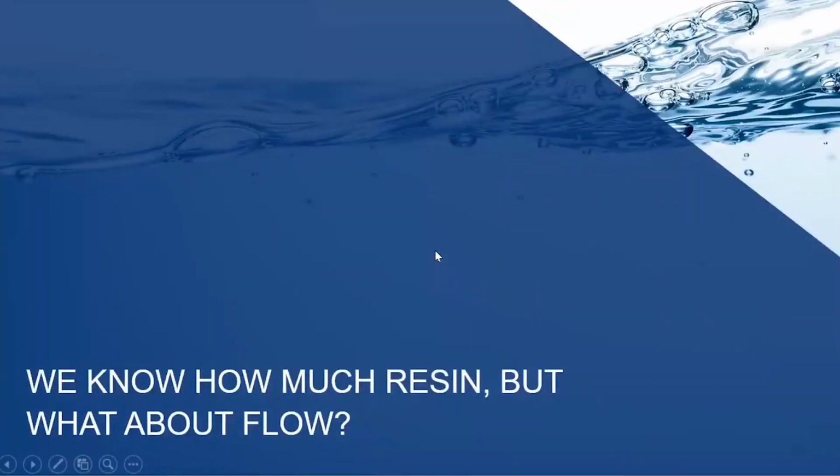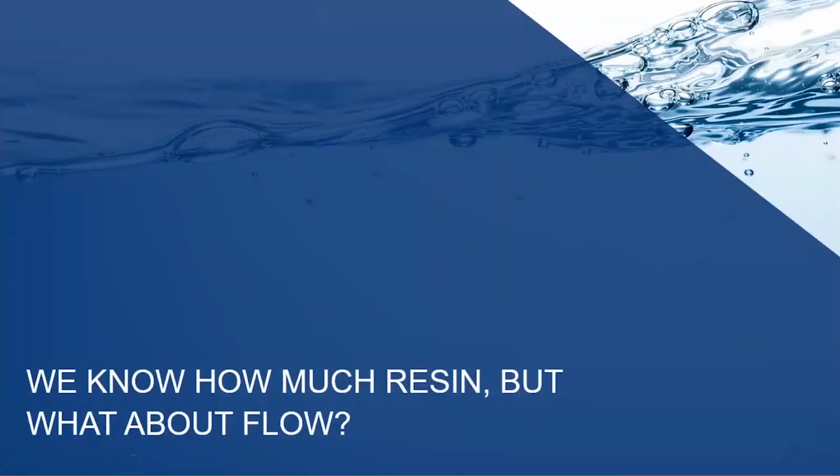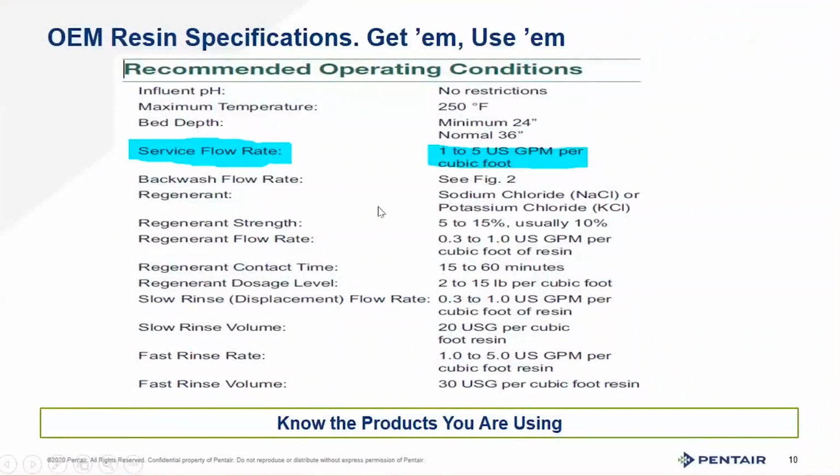So we know how much resin, but what about flow? That was that 400-pound gorilla in the room that we haven't even scratched, right? That amount of resin can treat that amount of hardness in a given day. But what about the reality of pushing water through it? And how much water is my customer actually using? How quickly? So I suggest always going to your OEM spec sheets.